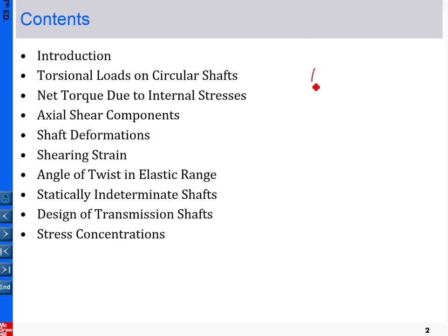Okay, so basically here we consider a circular shaft, and the torsion applied is simply to twist the shaft. Say this is in equilibrium, so the torsion we use T to apply. In this chapter we're going to study how to describe the deformations of this circular shaft, and from there how to calculate the stress, and actually this is a shear stress.